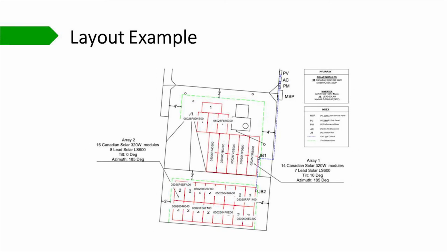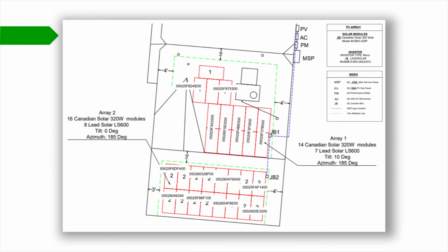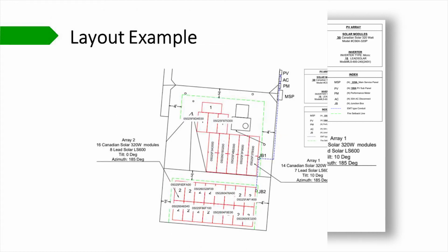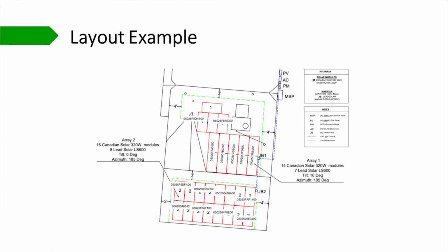During the installation process, please make sure to attach the MAC ID labels and not the serial numbers to the layout map. The MAC ID is the square label with a QR code. This will assist in the commissioning process and help to identify the exact position of the microinverter and its associated modules should any troubleshooting be later required.